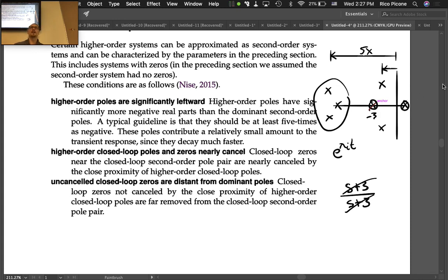And you put a 0 on it, it does cancel, and in terms of forced response, technically, it will be stable. However, if there's any disturbance in your system from equilibrium in that modal direction, which doesn't make sense from what we've talked about so far, but you might have a concept of what that might be, the system will still go off to infinity. So it's still unstable even if you have pole zero cancellation of an unstable pole.